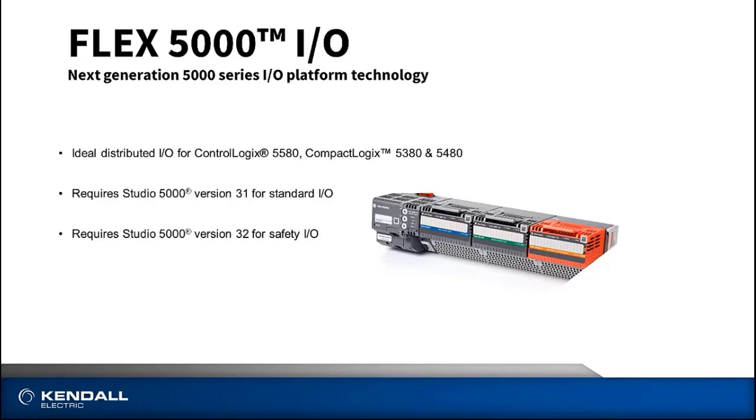Also, similarly, in terms of software and firmware, if we're going to be configuring the standard I/O modules of Flex 5000, we need to be at version 31 of software and firmware. If we're going to be deploying and configuring the safety I/O modules in this platform, we need to be at version 32. And it's also important to note there, similar to the point I/O structure, we have the ability in this I/O structure to mix and match both standard and safety modules in the same chassis.